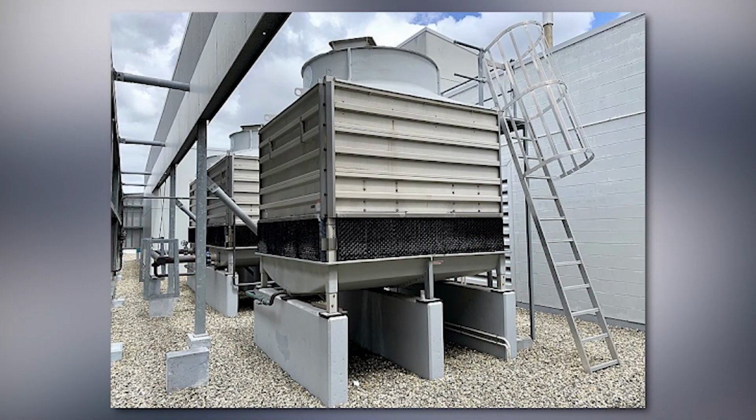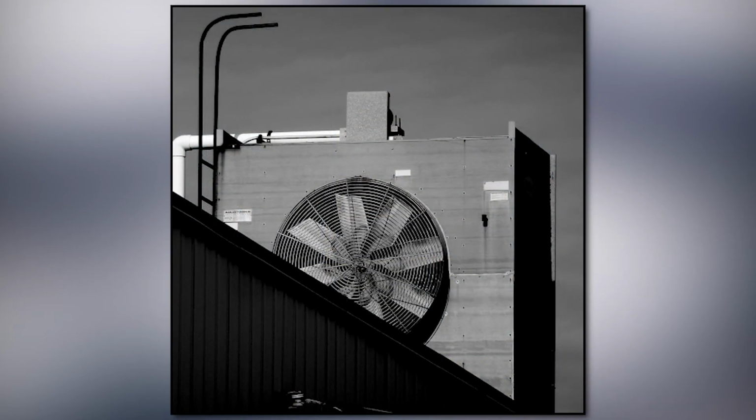Cooling tower sizing is also an area where money can be saved. Ensuring you have a properly sized cooling tower for the amount of chilled water that you need is a key way to minimize waste. If you have a very large cooling tower that runs a significant amount of time, installing a variable frequency drive for the fans or installing premium efficiency motors for the fans may pay off for your facility.